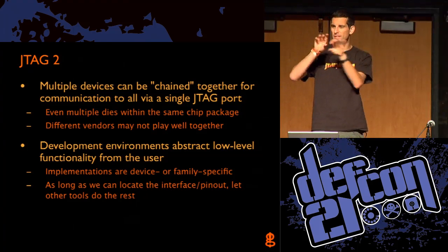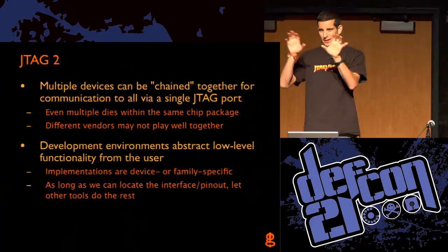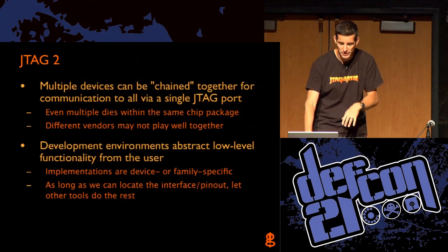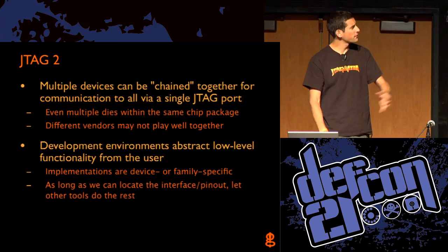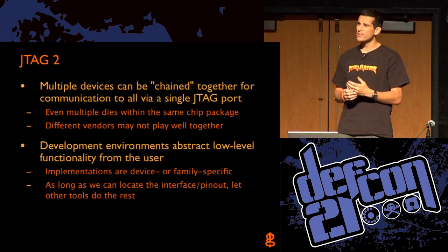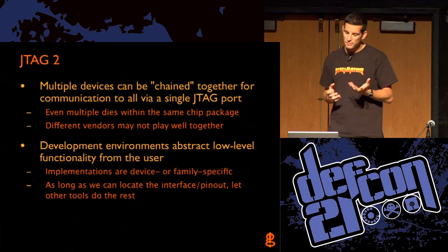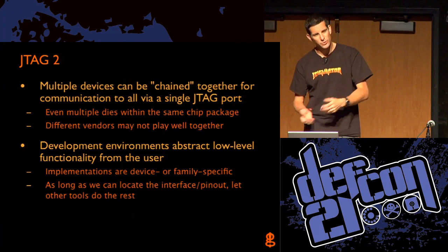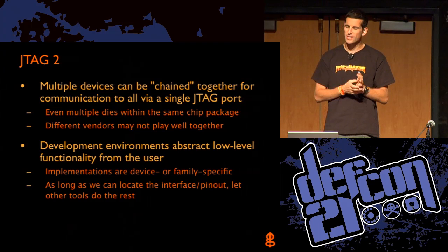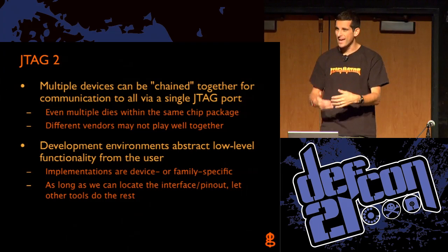Because JTAG ends up being a gigantic shift register of varying lengths once you figure that out, and I'll talk about that. And the vendor, again, will abstract all of that low-level stuff. And we don't really care. Once we know the pinout, we can then load legitimate development tools that the vendor makes or some of the open source stuff that's out there, and then start our attack process.